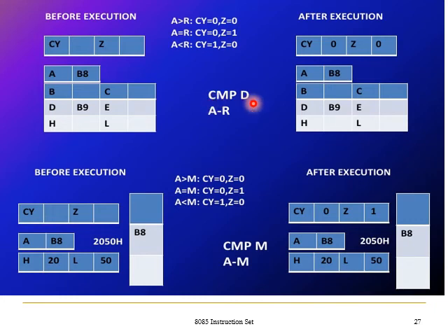Compare D. It is going to compare the content of the D register with the A register. So the A register content is compared with the D register content. Obviously it is going to subtract. While subtracting, adding or doing any arithmetic operation, the flag registers are affected. By checking the flags, the microprocessor comes to a decision whether the given number is equal, greater or smaller, right?